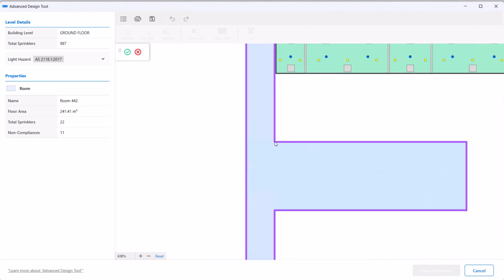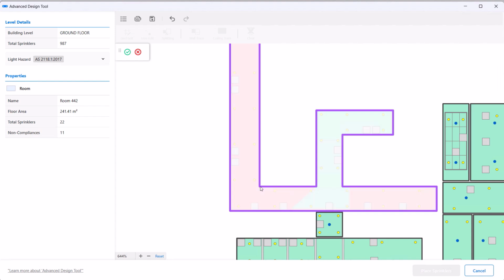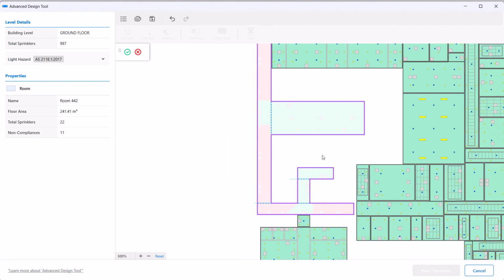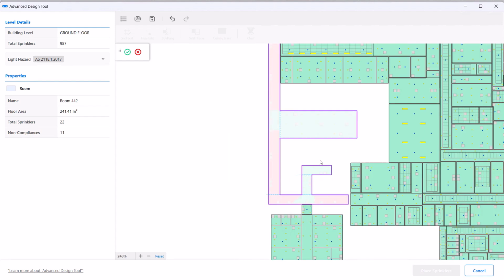Using the splitting tool, you will go ahead and split the complex room into square or rectangular shapes for Tandem to analyze. Holding the Shift key down allows you to generate straight lines as you are splitting rooms. The splitting tool allows you to create digital walls for Tandem without affecting your architectural Revit model.